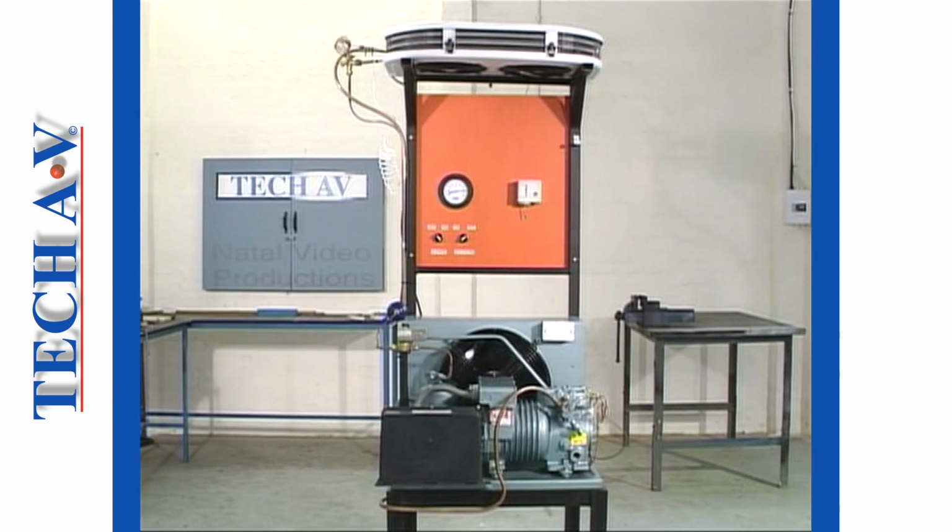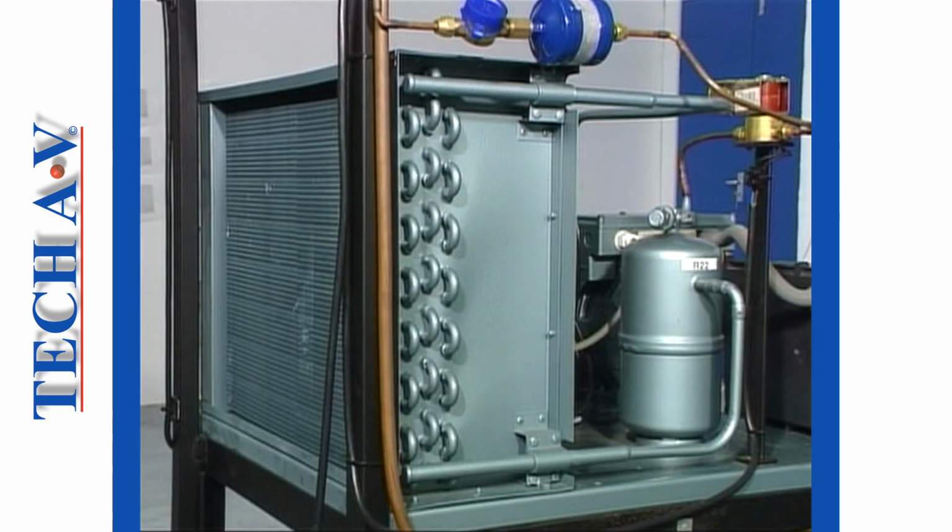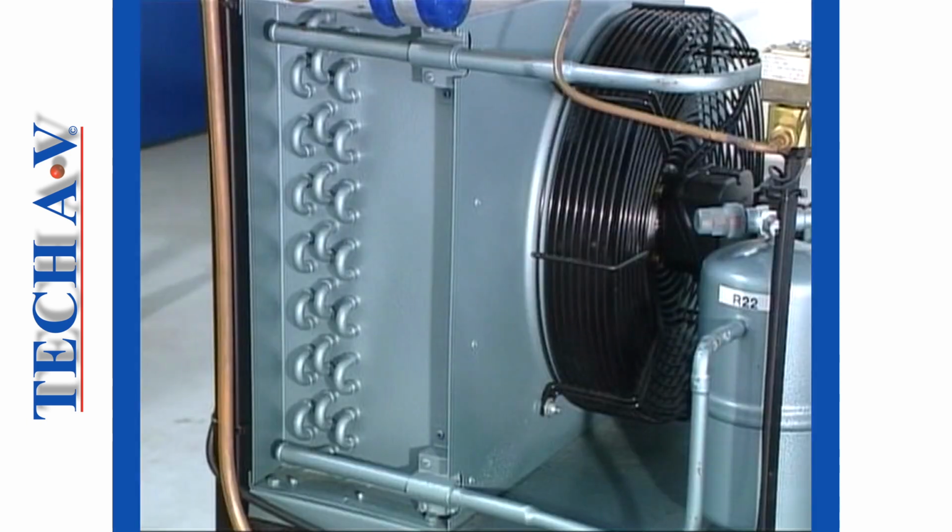Let us begin to identify these components on our model unit. Here we have the compressor. This particular compressor is known as an accessible hermetic type. The next component is the condenser. A dominant feature of our condenser is the large cooling fan attached to it. This is where our unit derives its classification as being air-cooled.